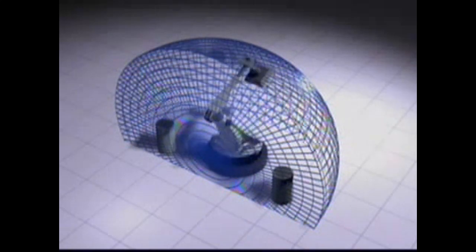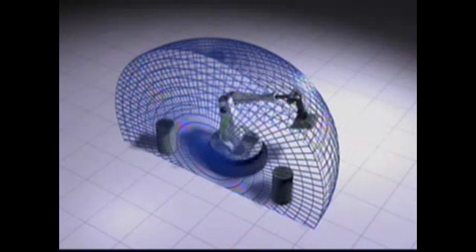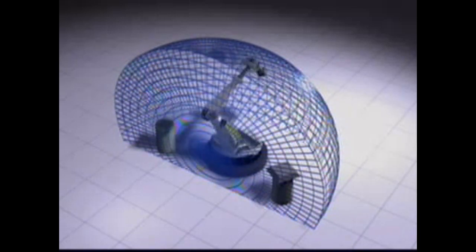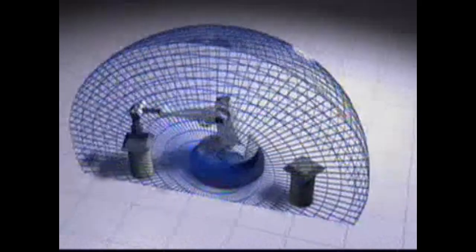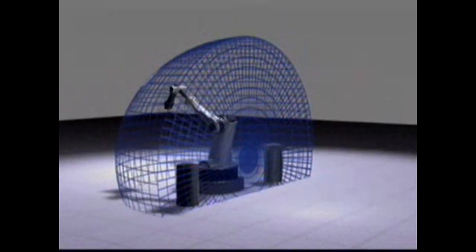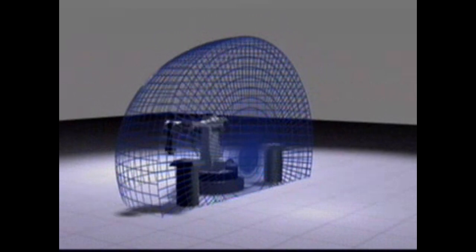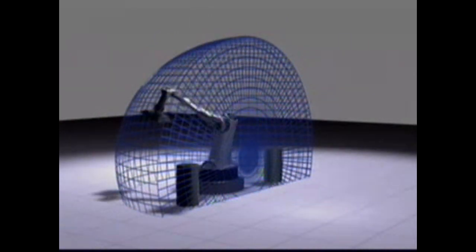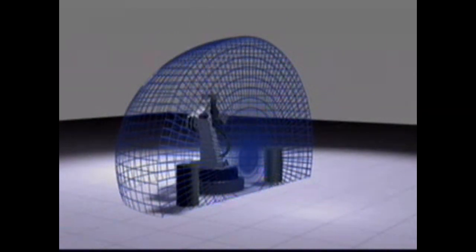If a limiting device has been installed, the robot's movement for a particular application may be restricted to a smaller area, called the restricted space, shown here in blue. A limiting device restricts the robot's maximum space by stopping all robot motion independently of the control and application programs. Restricted space may change if the robot is installed in a different application and with different limiting devices.